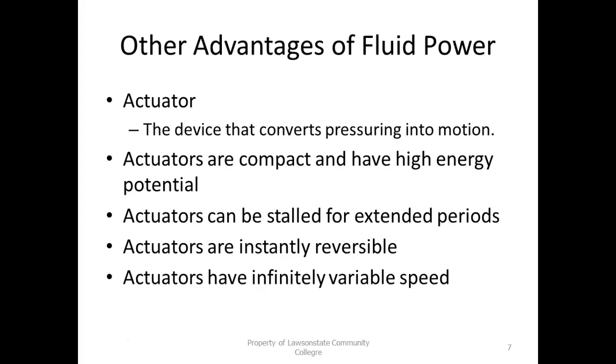They're compact and have high energy. We already talked about that. Another big advantage of these fluid power systems is we can install these actuators and stall them. We can't stall electric motors because if you stall them, they're going to burn up. But these guys don't care. You can leave that pressure against one side of that actuator for doomsday, and it'll stay there and won't hurt anything. So any situation where you're going to have to stall the actuator, it's probably going to be fluid power.